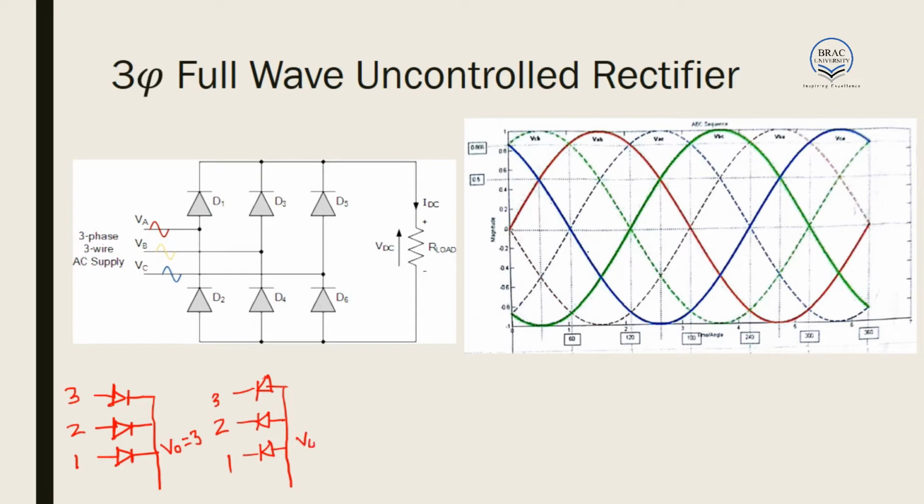The V output over here will have the minimum value, because if this is the minimum value, this has to be 1. If this is 1, this becomes reverse biased, this also becomes reverse biased. As a result, V output will have to be the minimum value. So we are considering ideal diodes. In this configuration, the V output will be the largest value of the input, and in this configuration, the V output will be the smallest value of the input, which will be useful here.